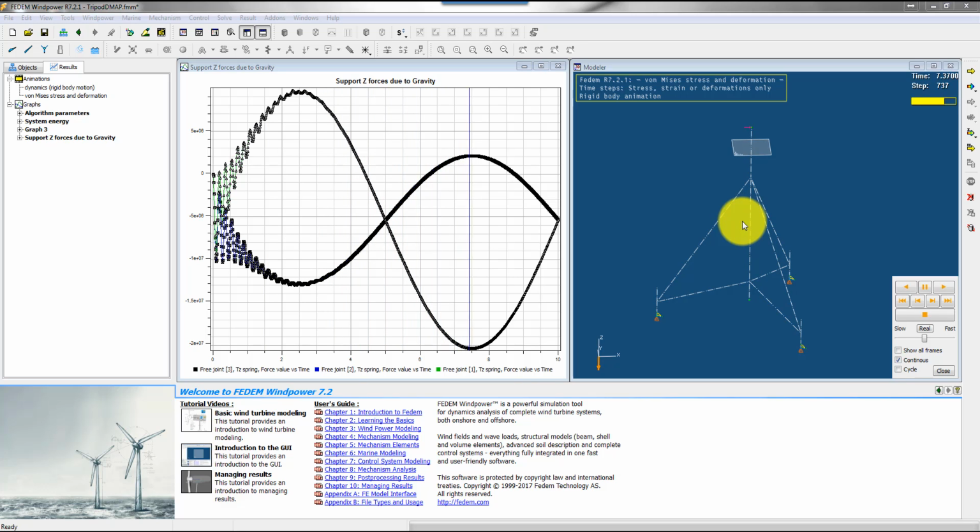If you have questions regarding this, you can contact me. It's quite straightforward as long as you remember to copy the OP2 files to the same folder as the Nastran bulk data file. And you also need to put your DMAP in the same location at the time being. In future releases of Fedem, this will be automatically taken care of.